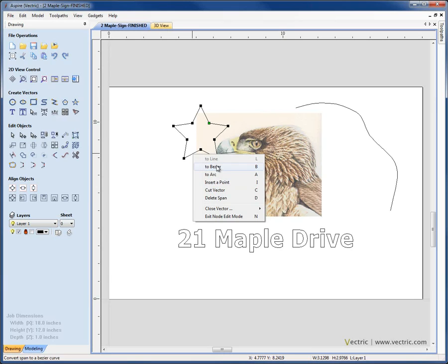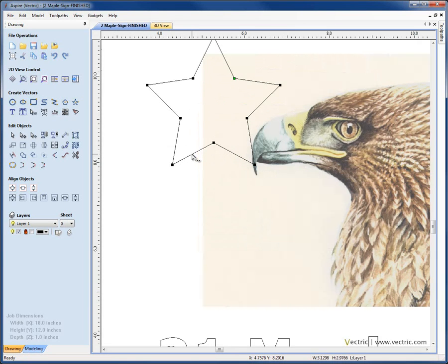You can see in these right mouse click menus there are often letters on the right hand side of the menu associated with the command, and all of these are shortcut keys that I can use in lieu of right mouse clicking and coming into the menu. For instance, in here you can see if I want to delete something, I hit D. I can show you that now by clicking here, coming over the span here and hitting D on the keyboard, and it's going to delete it. That's how the shortcut keys work that you see within those right mouse click menus.